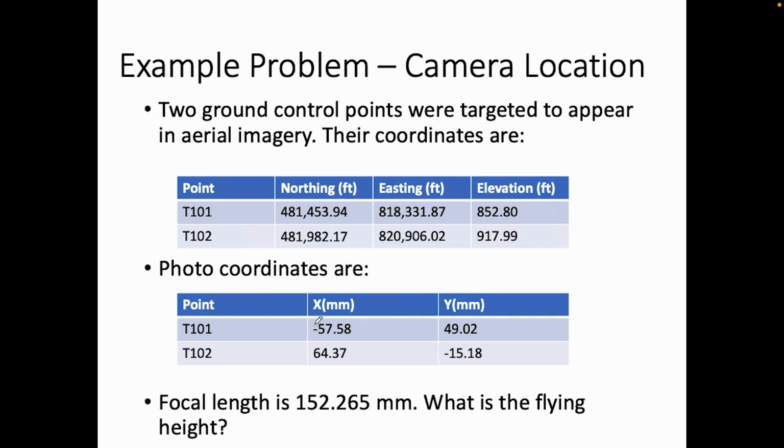Then we're going to take the difference of the position in the photo coordinates. We're going to take this number minus this number squared, plus this number minus this number squared, and we'll get the distance in the photograph. And then we'll use those 2 distances as our numbers in that ratio that we saw before. And what was that ratio? I think it was H over W.